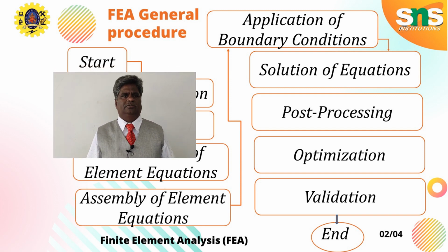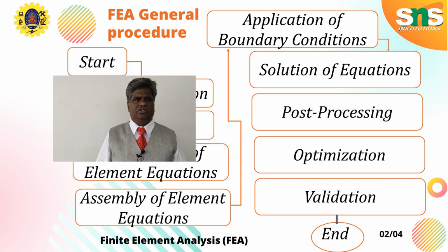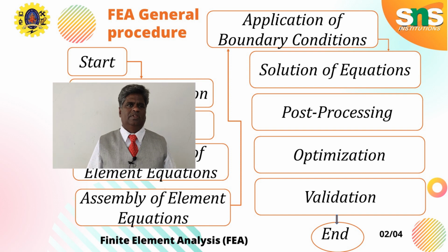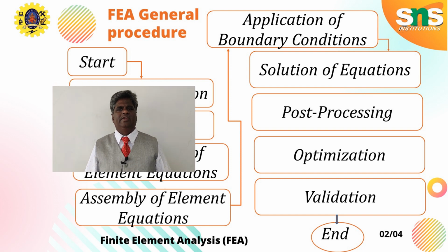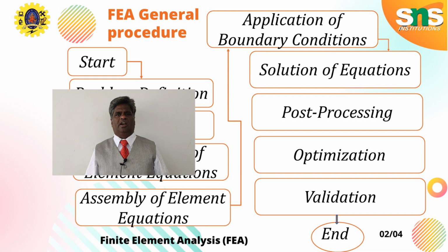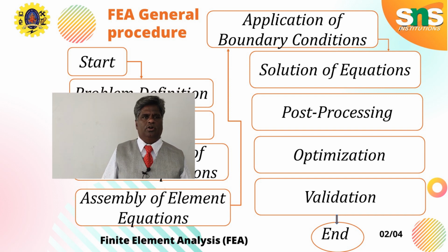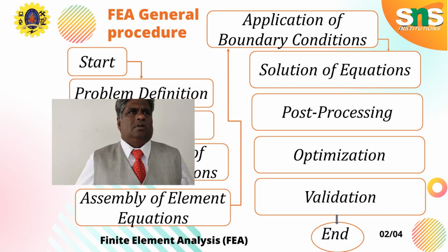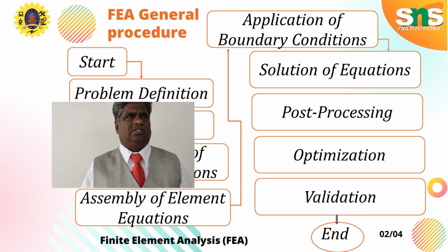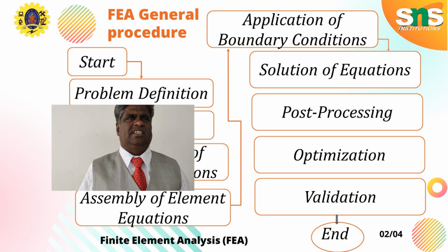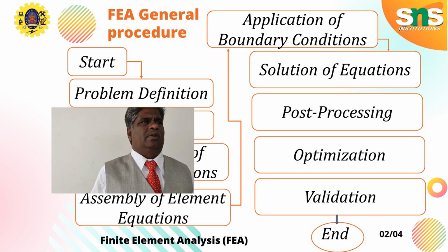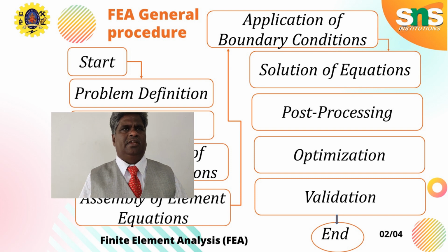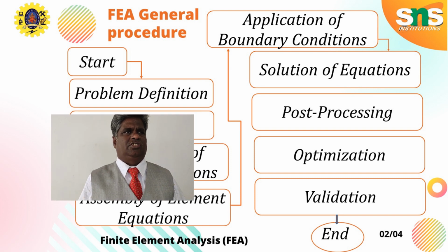Solution of equations: the reduced system of equations is solved to obtain the nodal displacements, which represent the deformation of the structure under the specified load conditions. Post processing: the stress and strain in each element are calculated from the nodal displacements and used to evaluate the safety and performance of the structure.